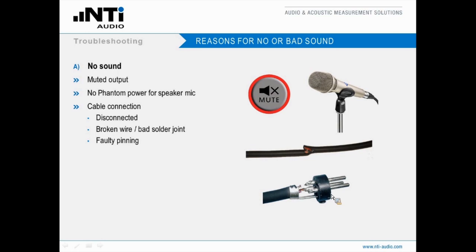Another reason could be buried in the cable connection, either because the cable is just disconnected, or we are facing a broken wire or a bad solder joint, or we have a faulty pinning in the connector. All these problems may occur and can cause a missing sound in your setup.